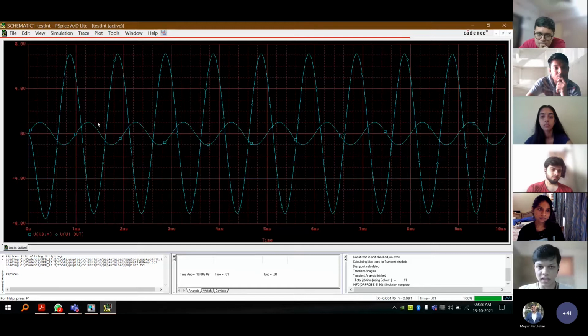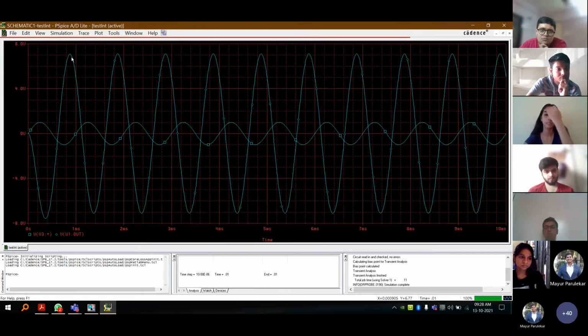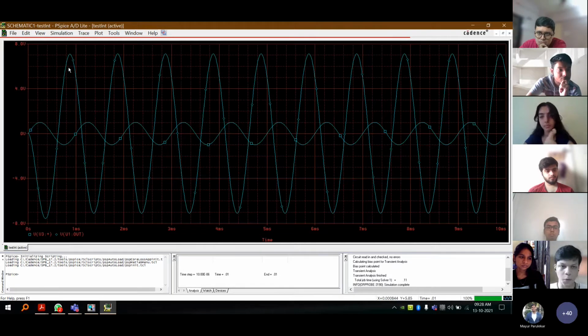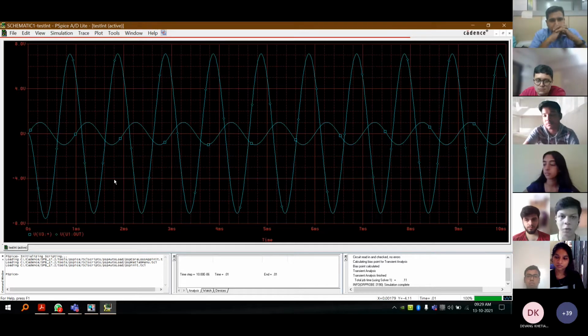You can see this small sine wave here as our input voltage, and you can see this bigger minus cos wave here as our integrated output. So you can see that there is a phase change happening here. That is obviously because, first of all, we're putting our input at the negative terminal, the inverting terminal. And secondly, because this op-amp is not ideal, there will be a certain slew rate. If you know what slew rate means, it's basically the op-amp's delay in reacting to input changes. That will increase as we go on to higher frequencies. At 1 kilohertz, that's almost not an issue for us.